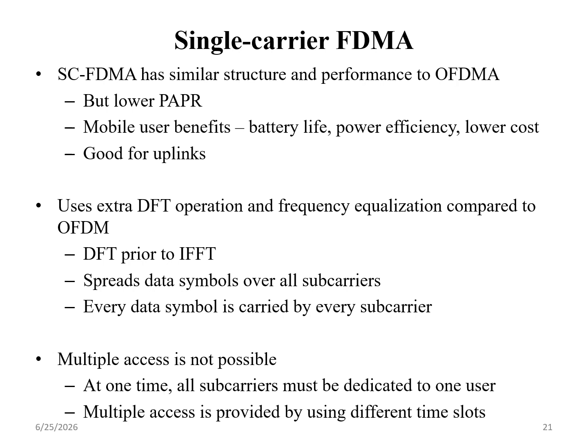Why? Because the disadvantage in OFDM is fulfilled with the help of single carrier frequency division multiple access. So DFT prior to IFFT, that we know, spreads the data signal over all the subcarriers. That was the point. Every data symbol is carried by every subcarrier. The data signal should be spread, or given, to all subcarriers.